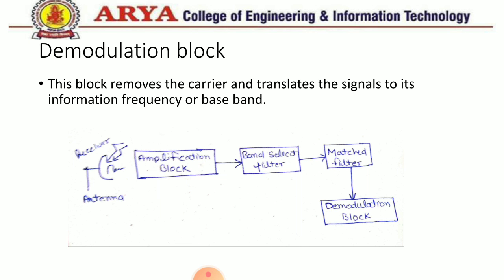Now let us take a quick review. So the radar receiver has four basic functional blocks, and each block has different equipment, circuits and components. So if I receive a signal from the radar receiver antenna and the signal has low strength, then at the demodulation block, information may be lost because of weak strength.